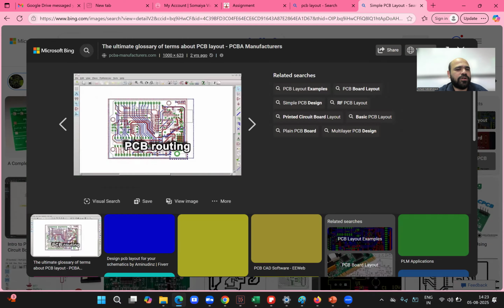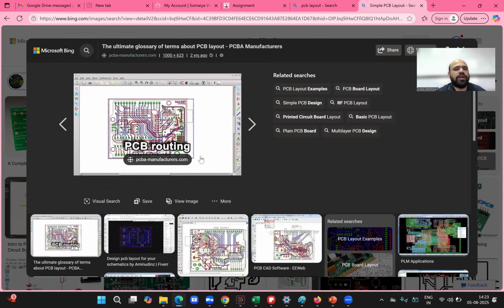You can also use auto routing, but you have to maintain a single condition that your PCB, ideally 99% of the projects, should be a single sided PCB and should not exceed a standard PCB size of 100 by 150. That is the dimensions we generally get with the PCB. But if you have something special, we can discuss, and it's definitely allowed.